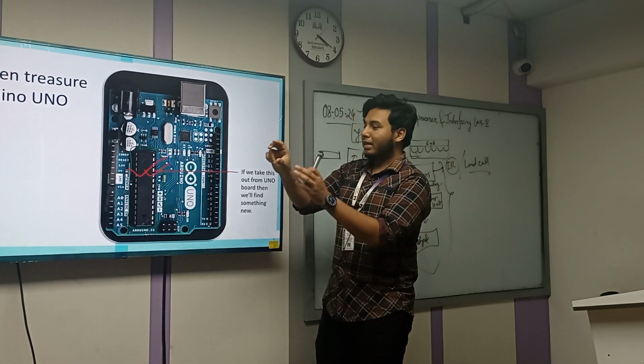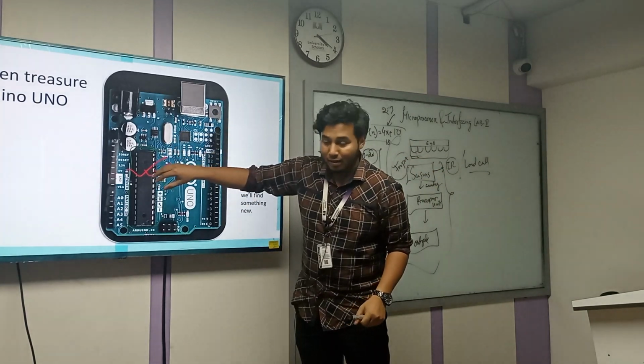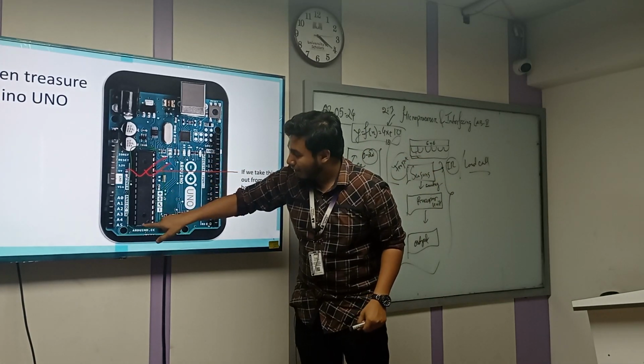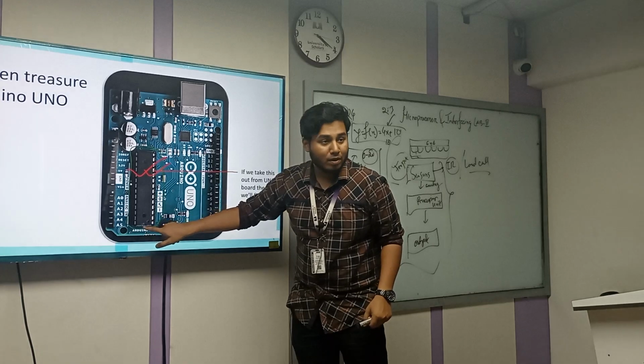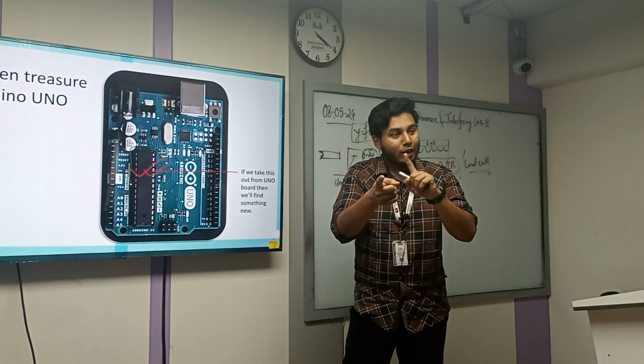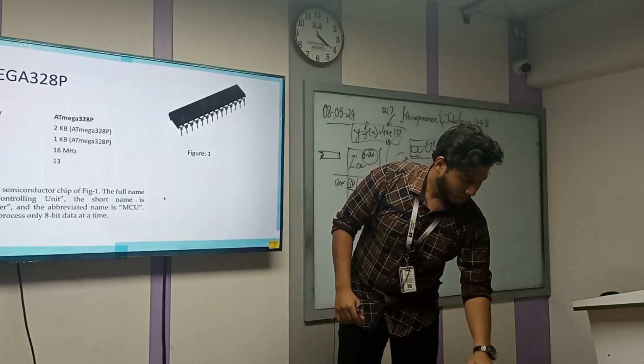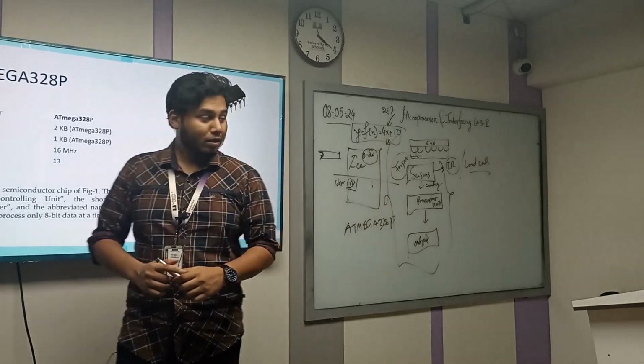The chipset you can rotate this way, but if we set it down here, you need to look very carefully at that part, because the pin numbers 1 to 28 will vary with its rotation.